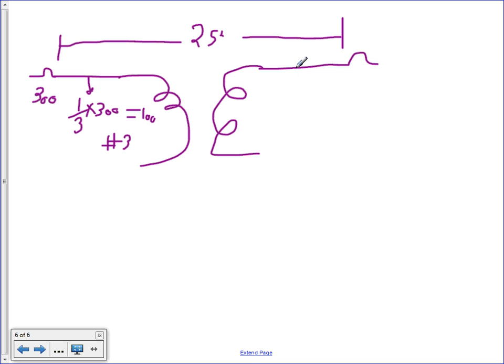Now you go on the secondary side to size your conductor here. Piece of cake. You're going to do the same calculation, guys. 1/3 multiplied by the 300, except what do you need to do with the voltage? Let's use the voltage 480. Let's do a realistic one, 480/208. I need somebody to do the math on that for me, will you? Because now it's complicated. Multiplied by 480 divided by 208. 480 divided by 208, how much? All of them, the whole thing.